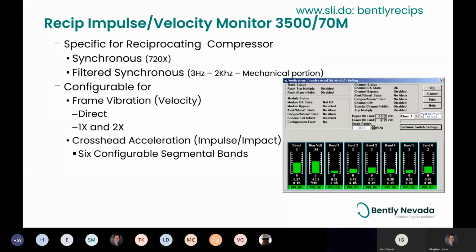But when it goes through the valves, it makes a noise. So it's very high frequency. So you don't want to confuse the amplitude of that high frequency noise with that of the impacts. So we filter it for this range, and then you only get the impacts.